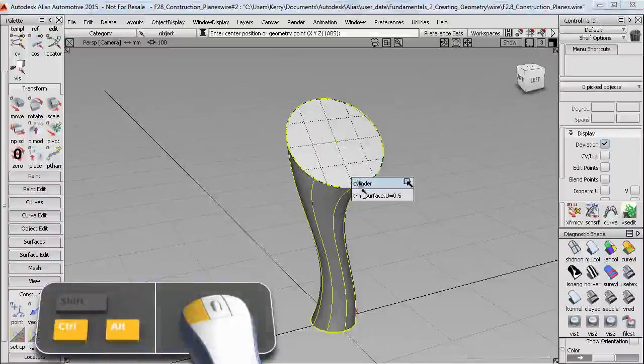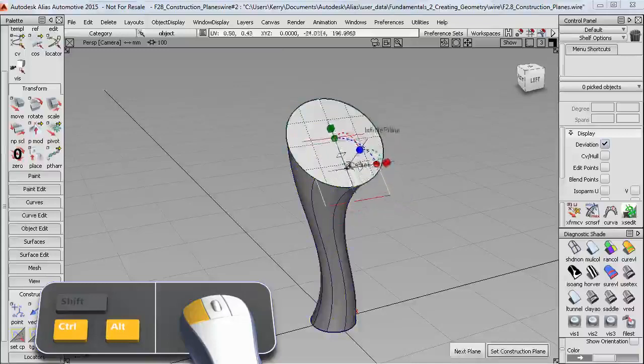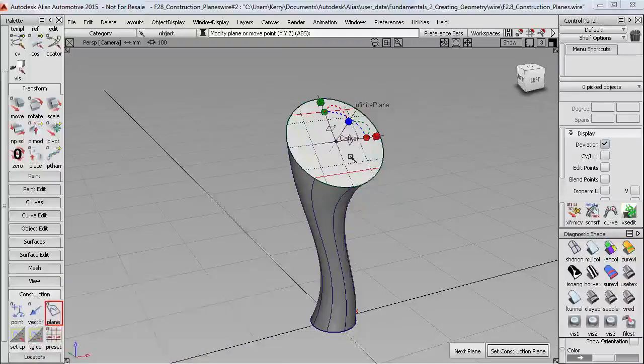And if you get the pick chooser with curve snap, then you need to keep the mouse button held down and go over to the black pointer and then drag to the point you want to snap to. And the key is not to let go of the mouse button. And to make sure you can snap in the center, just check that your curve snap divisions are set to 2.